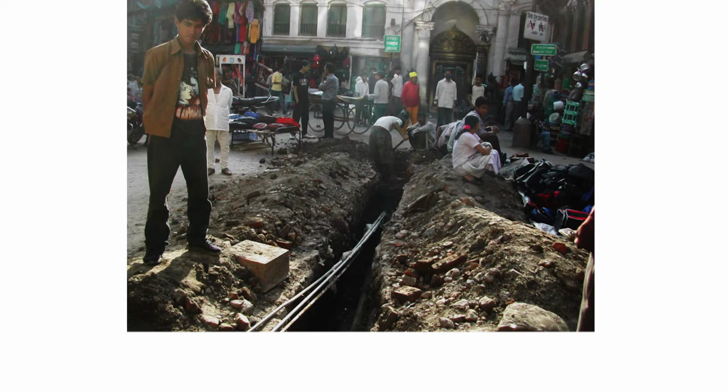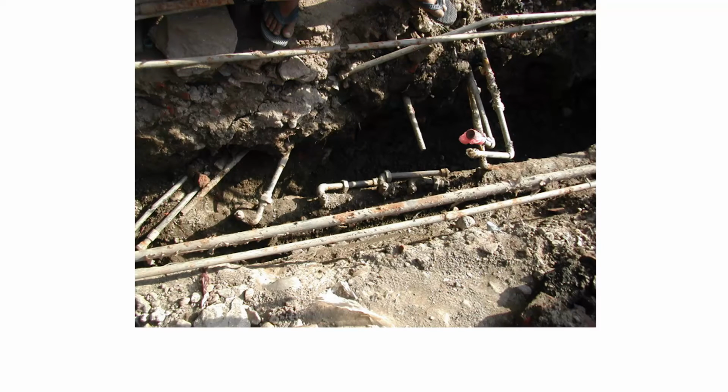Here's a look at a pipeline repair project underway in a neighborhood. Notice the multiple pipelines laid next to each other. In most neighborhoods, there's no record of where the water and sewer lines actually are. Here's a closer look. In the 1990s, several international firms looked at this infrastructure to estimate what it was worth. Most concluded that it all had to be replaced. You couldn't put these pipes under any pressure, they would burst. These pipelines are all subject to negative pressure and water infiltration. This means that contaminated groundwater will get into the water in these pipes. So water from the pipes is not going to be potable.